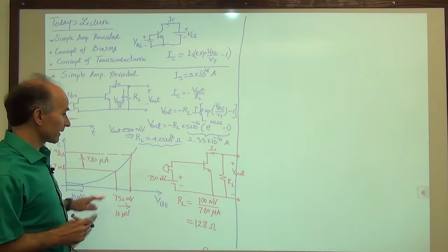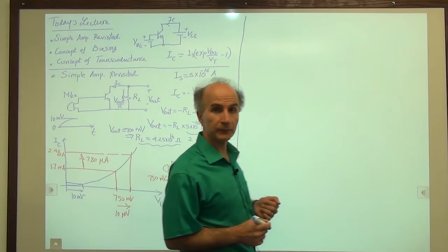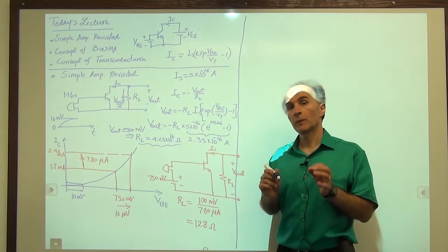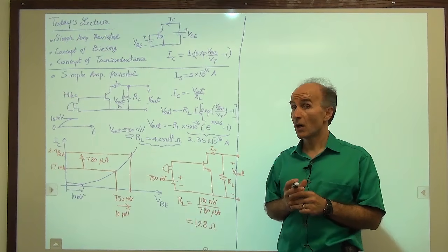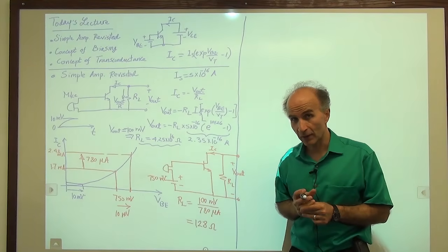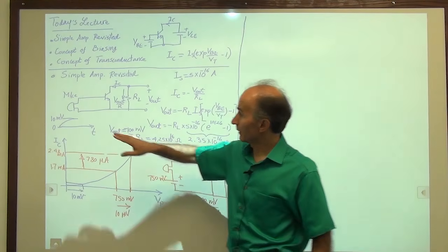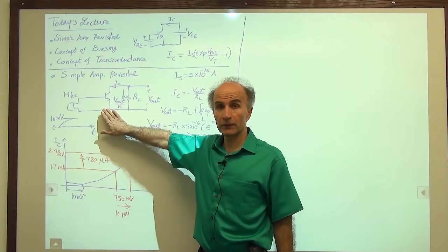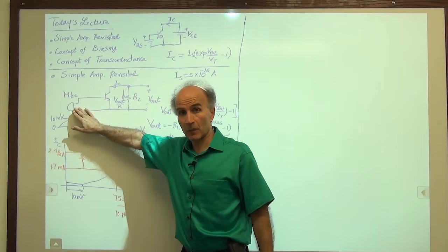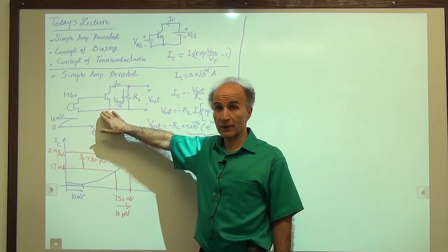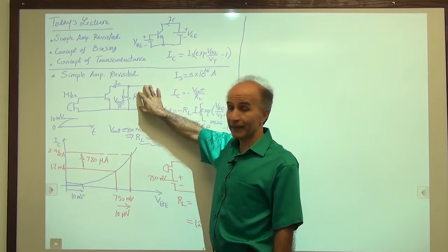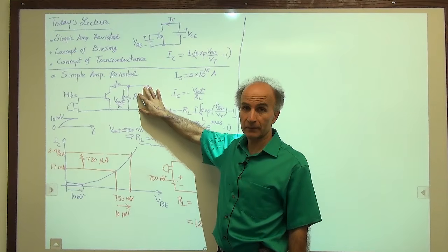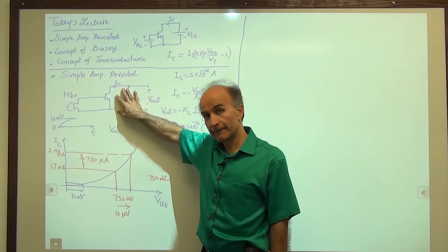So let's take a step back and see exactly what happened here. What we see is that the bipolar transistor is not capable of amplification if we just give the signal directly to its base emitter voltage. The signal is small, the base emitter forward junction is very small, the current is extremely small, so we can't have any voltage at the output. Right? This is not usable.